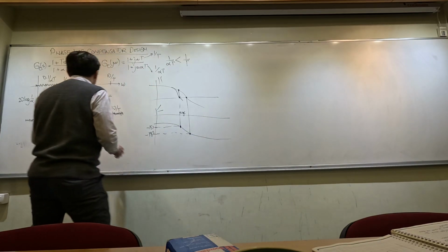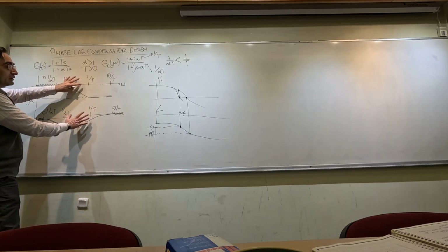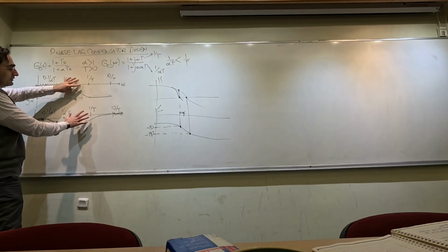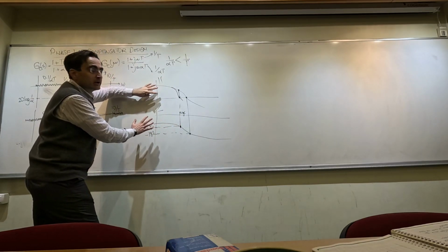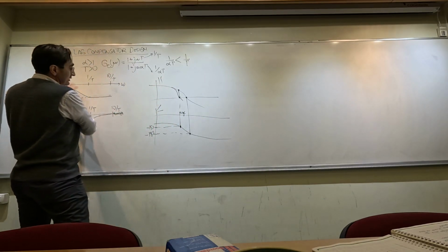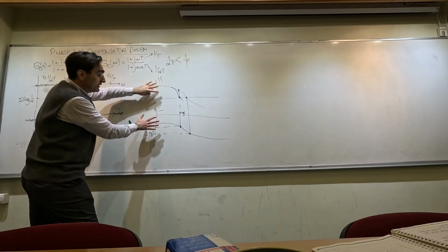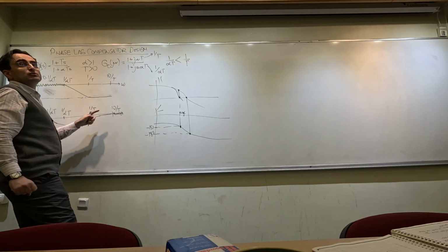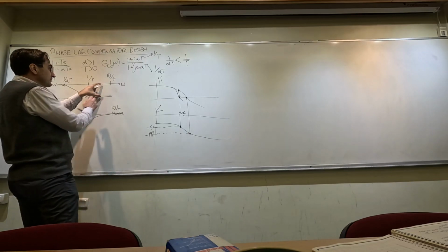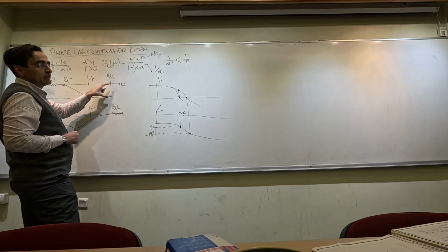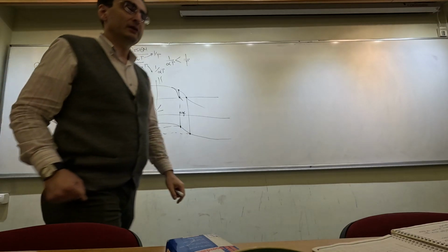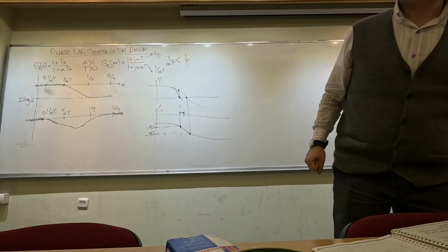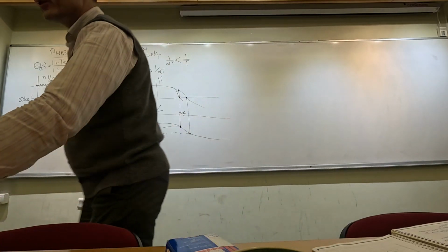That is why usually we will try to put this transfer function as far left as possible. So we are going to place this thing somewhere around here so that this phase decrease does not affect us. But we would still get the gain decrease here, which we are going to benefit from. That is how we're going to design a phase lag compensator.